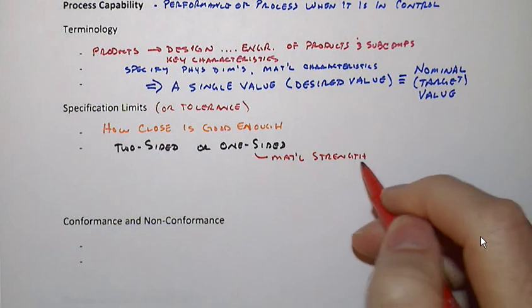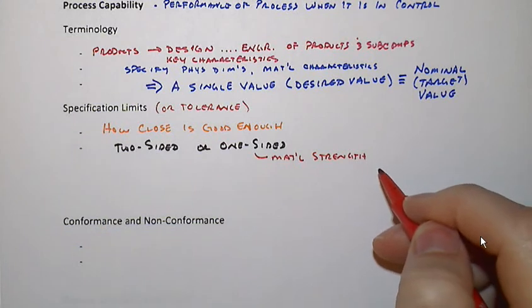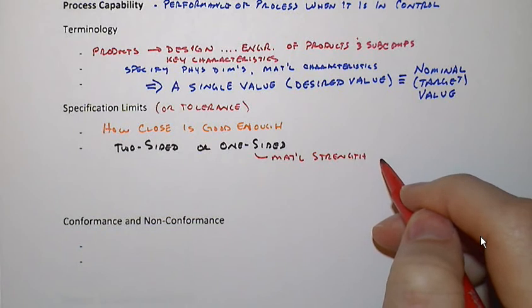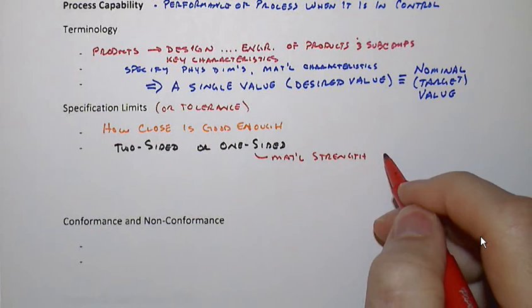For concrete strength, for instance, we might be specifying 4,000 psi. For above ground structural members, for foundation work, that might be 3,000 psi. And we don't really care if we get concrete that's actually greater in strength. That usually just costs somebody more, and they want to provide something for free.